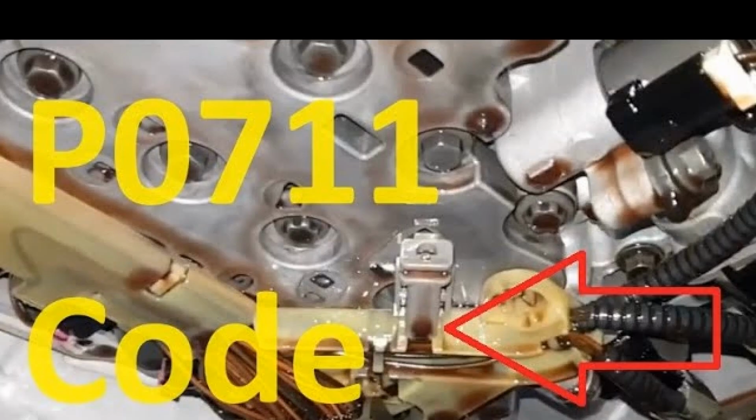Error P0711 is considered a generic code as it applies to all vehicle makes and models, although the specific repair steps may vary slightly depending on the model. The transmission fluid temperature sensor, TFT, is part of the transmission fluid pressure valve, TFP. It is a thermistor that changes value depending on the temperature. As the temperature increases, the resistance decreases, and as the temperature decreases, the resistance increases.